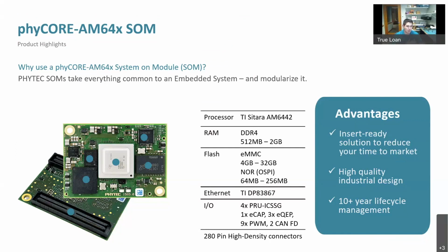If you use a SOM, when you go to qualify your product's electromagnetic emissions, you can trust that we at PHYTEC have pre-qualified the SOMs so that you don't have to worry about that being a point of failure in your qualification in your new design. At the same time, you can shrink your bill of materials. You can let PHYTEC manage all these common circuits revolving around the application processor. That would include, as you see here in the slide, the memory, flash, an Ethernet PHY if you opt for that, and then the high density connectors as well. These are all components that allow you to very easily work with the SOM and then offload a lot of the worry with PHYTEC.